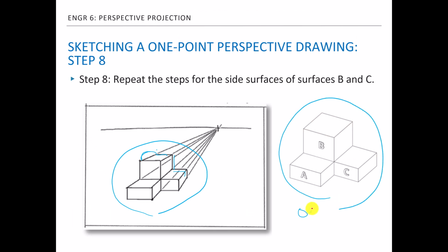This is actually orthographic. So here, as you can see, regardless of where that is located, this height and that height are identical. Okay, but in here, this height is higher than the back line. As it moves towards the vanishing point, meaning that the object gets farther away, this height gets smaller and smaller. Okay, so this is a perspective sketch, and that's an orthographic object. Okay, so this is how you can sketch the 1 point perspective drawing.